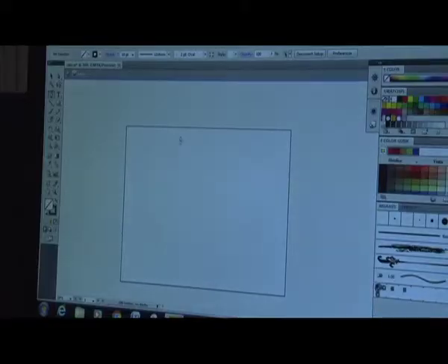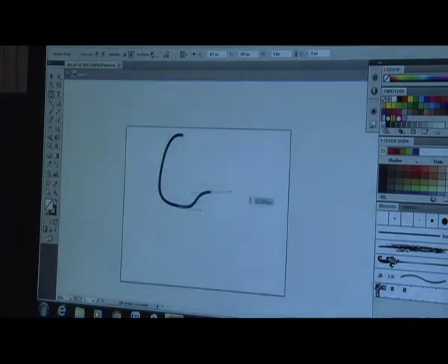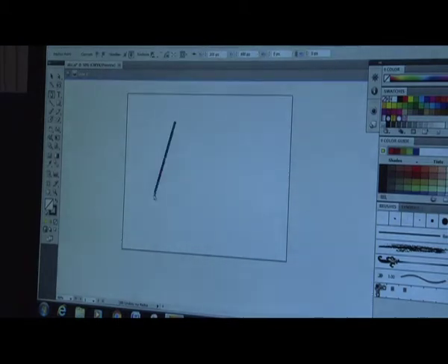Drawing tools in Illustrator. Pen tool. Select the pen tool and click once to add the first anchor point. Move your mouse to the next position and click again to create the second point. The two anchor points will be connected together. Continue doing this to create a W shape as shown. To draw a new line, click the selection tool, the black arrow icon, and click back on the pen tool again. To close a path, click back on the starting point to close the shape.